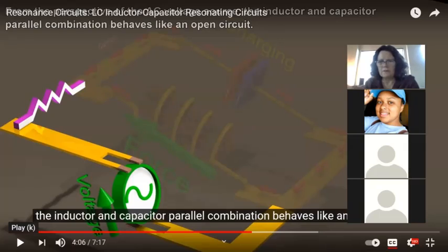But for right now, the heart of that is keeping the signal strong through this LC network that has very little resistance, and then using an active device like an op amp to amplify that and feed the output of the amplifier back into the input of the LC. So it keeps getting a bigger and bigger input until finally it breaks into oscillation. The most common way to build a good oscillator is to try to build an amplifier. And if you want to build an amplifier, you try to build an oscillator, but that's a whole nother thing. Sorry.